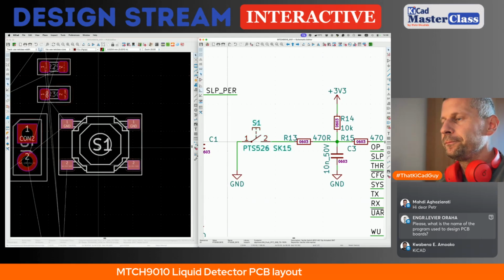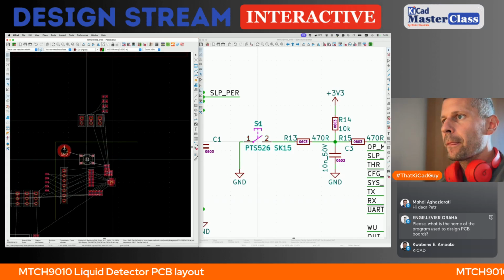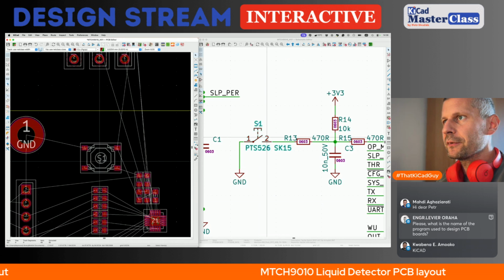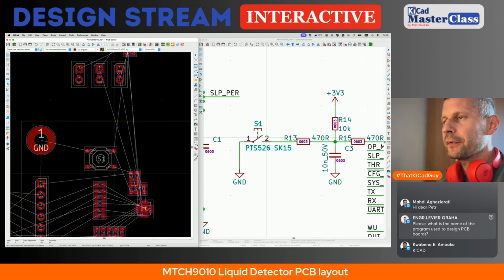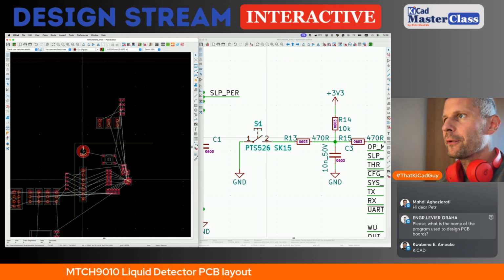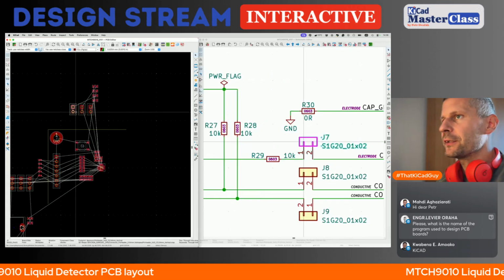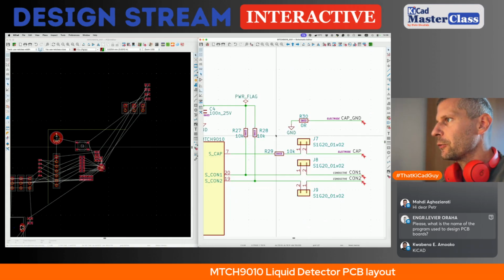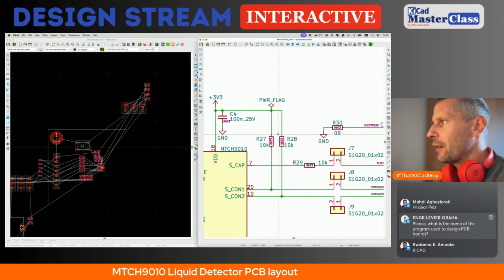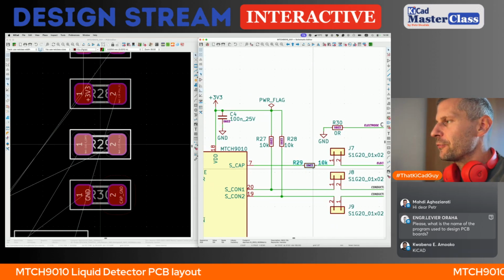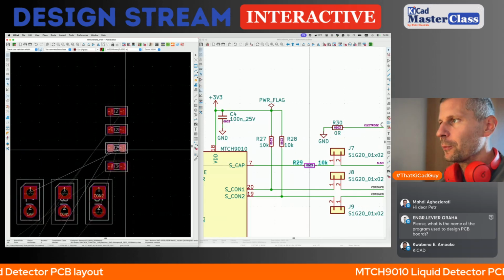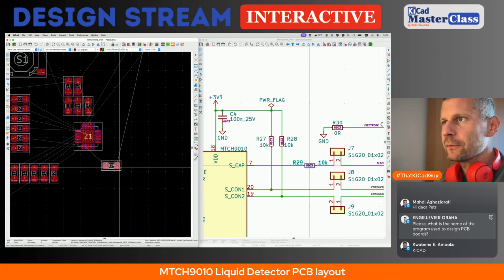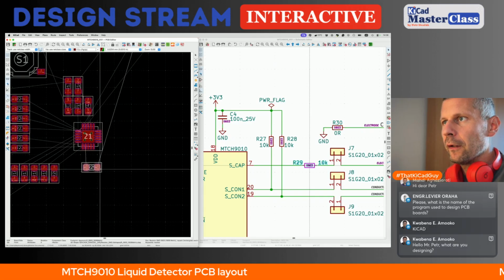And the button. I believe here is the perfect spot for this button with the label, future label, like here. It can work perfectly. These components are the electrode configuration jumpers, so let's focus on these components. We have serial resistors for the single-ended sensor coming from the pin number 7. Pin number 7 is here, so I will place it here.